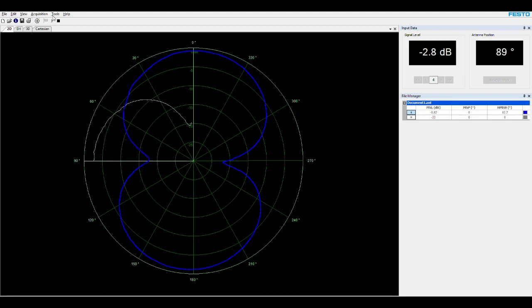So what we expect is that when we increase the distance, the received signal should be smaller according to Friis equation. But then the overall shape of the radiation pattern should stay the same, because the shape of the radiation pattern should not depend ideally on the distance if you go far enough. If you don't go far enough, then with the change of distance, you're gonna have different distributions of electromagnetic fields.